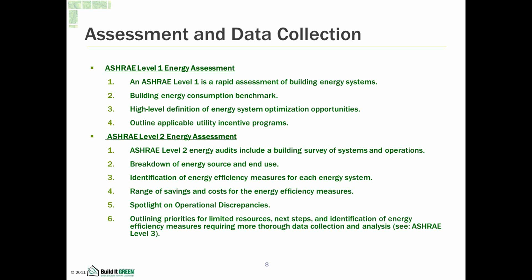You're going to identify what those deficiencies are and what measures can be identified to improve them, and also spotlight any operational discrepancies, what can help building maintenance operate the building more consistently, and outline priorities for resources, next steps, identifying energy efficiency measures, and also data collection and analysis. ASHRAE Level 3 is a more detailed assessment, and it goes into data logging, which most haven't gone into at this level of our industry, but I hope that's coming really soon.